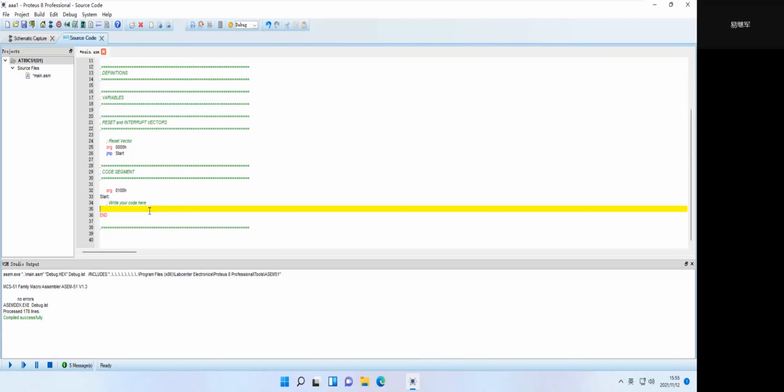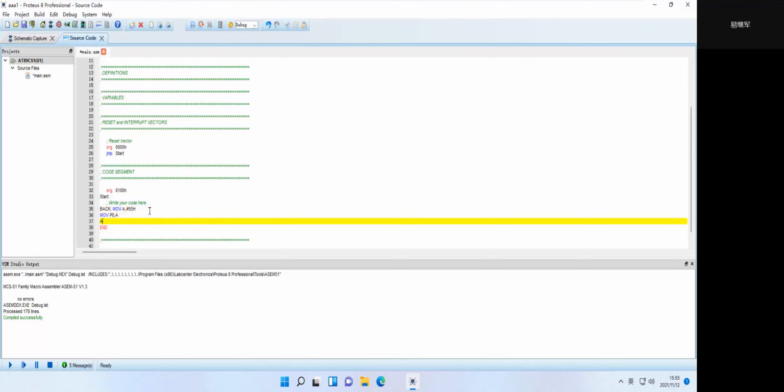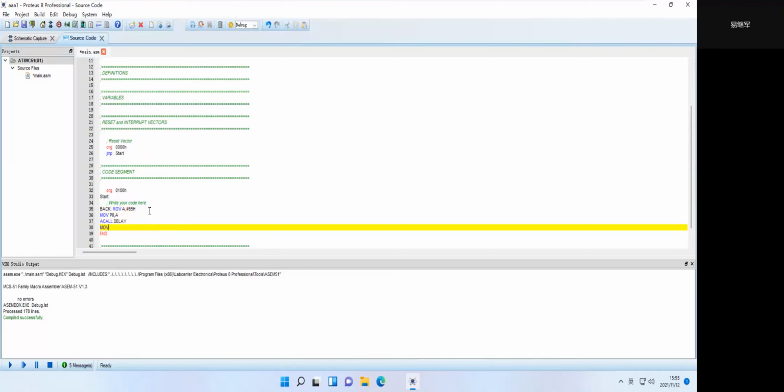MOV A, #55H. MOV P0, A. ACALL DELAY. MOV A, #0AAH.